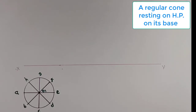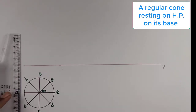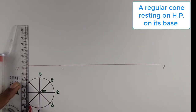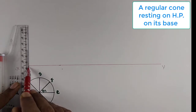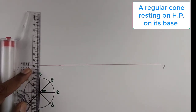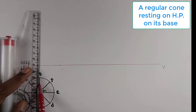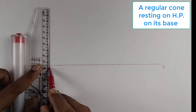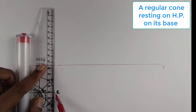Now the base is on HP, which means the elevation of the base lies on the XY line. So first we transfer all the projections, the base points and periphery points, onto the XY line with a light line.